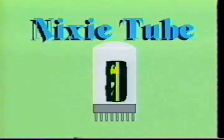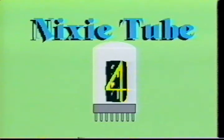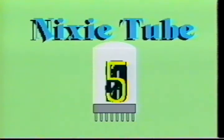As a voltage is applied between any single filament and the anode within the tube, the filament will turn on and glow a bright orange. Since the Nixie tube is a vacuum tube, it requires much higher voltages than does its solid-state counterpart, the 7-segment display. The Nixie tube requires a typical supply voltage of 100 volts.